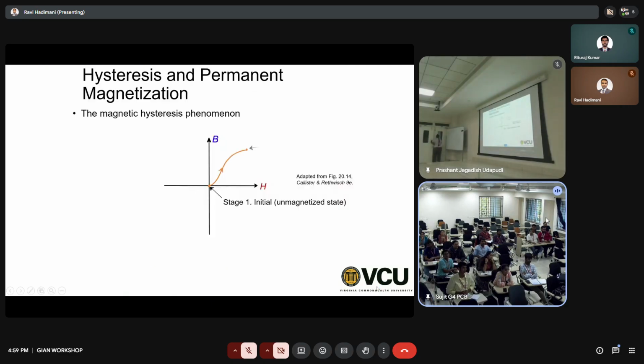Right, so now another important thing in magnetic materials is the hysteresis graph. Hysteresis graph is how the magnetic fields behave when you apply magnetic field and take off the magnetic field. So if you apply magnetic field for ferromagnetic materials, B or M, doesn't matter, there's a small difference, it will increase rapidly and then saturate. That is the hallmark of ferromagnetic materials.